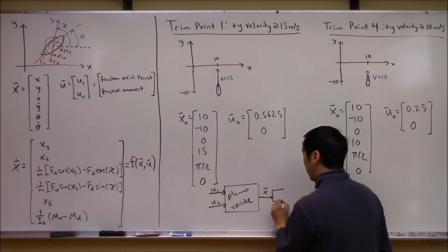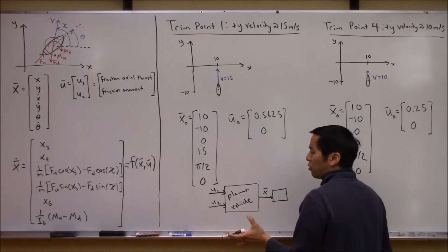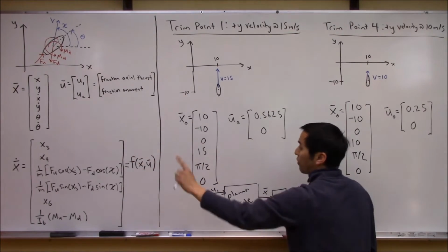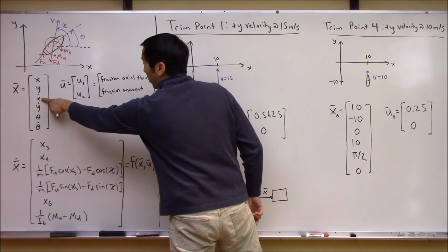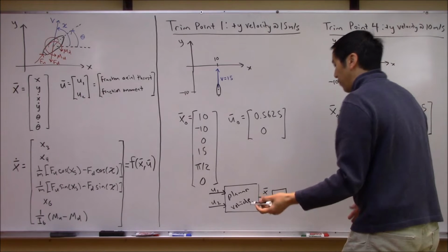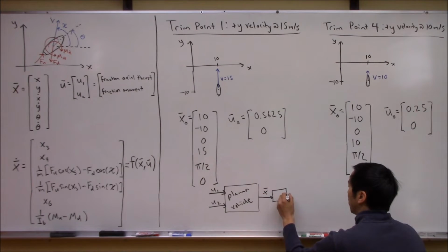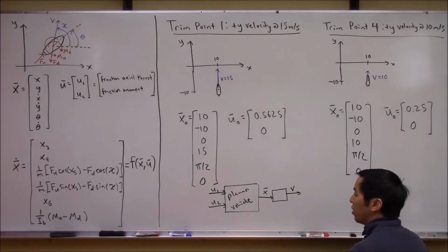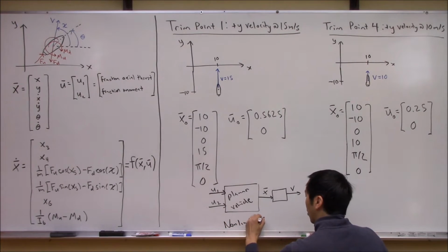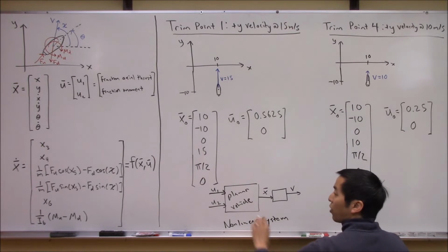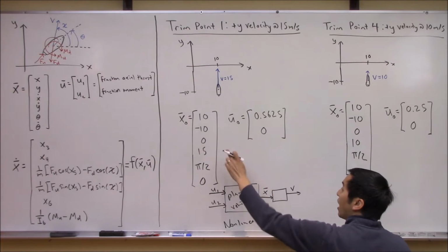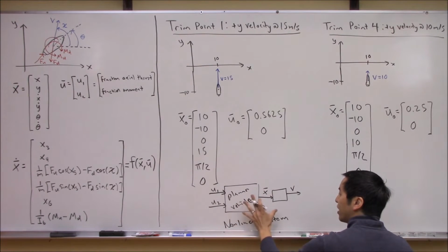And then what we did is we hooked up another block that would be able to compute some secondary parameters like the velocity. If you notice, the velocity is not one of the states. You have to compute the velocity by basically squaring this, adding it to this thing squared, and taking the square root of the 2 in order to get the velocity of the vehicle. So then we had another block here which computed something like velocity. So this was our nonlinear system. This was our dynamics over here. Here was a small little extra block to compute some secondary parameters. And now we have an operating point for this nonlinear system.